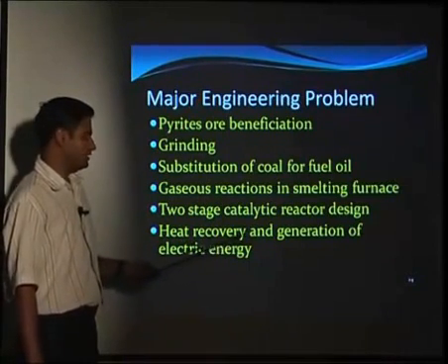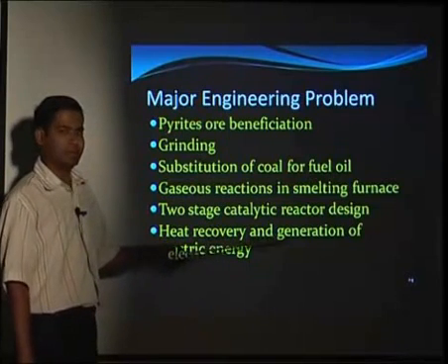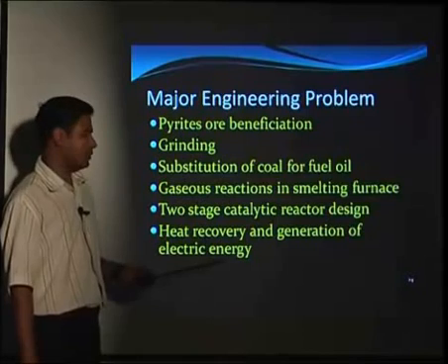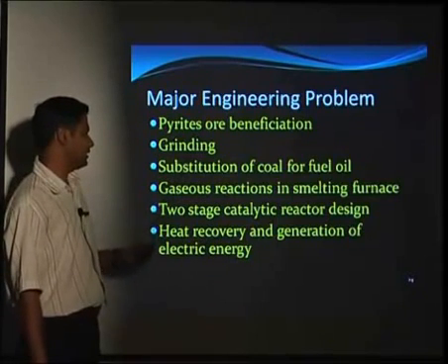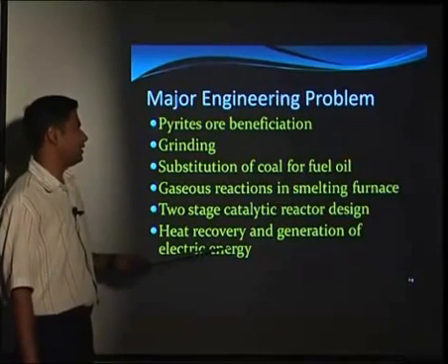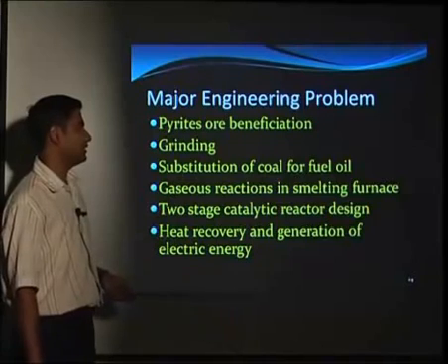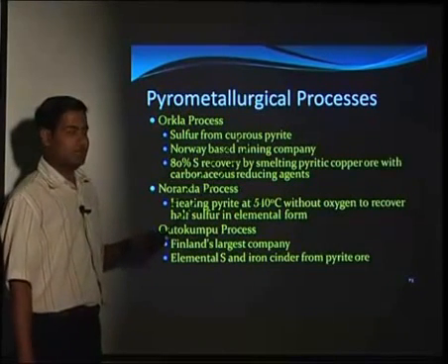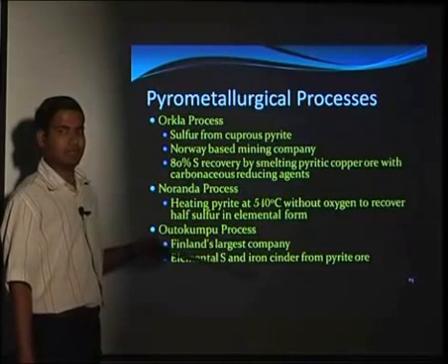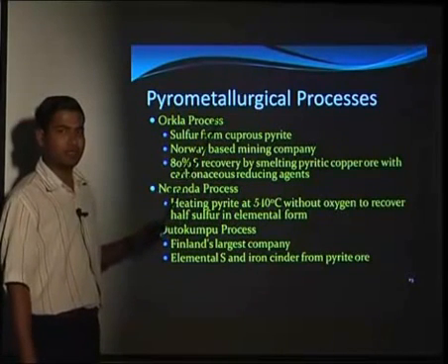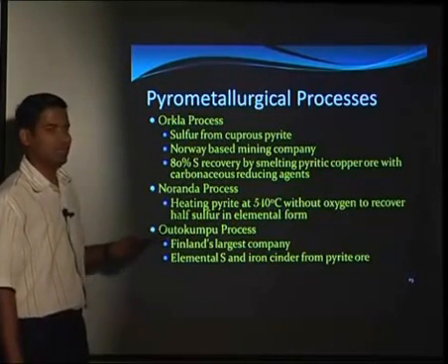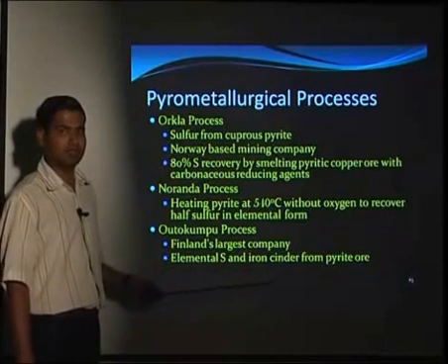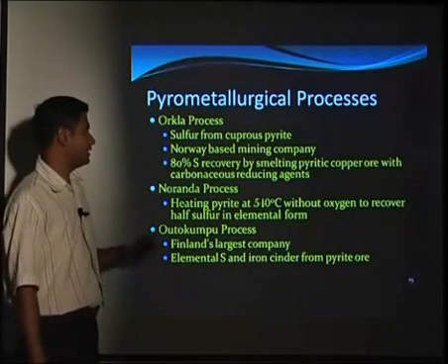So whatever the heat generated, we are recovering it to produce steam, and the steam we are feeding to generate process steam. So the design of this also becomes one of the major engineering problems in the sulfur recovery. Then we have seen the sulfur recovery from the Frasch process, then from H2S and from the iron pyrite. So there are other processes that were used to recover elemental sulfur.